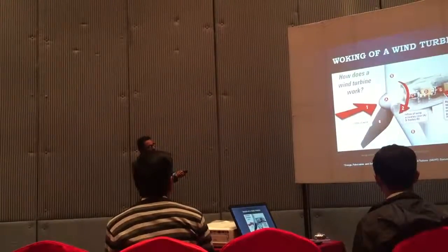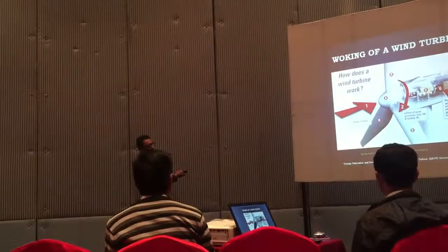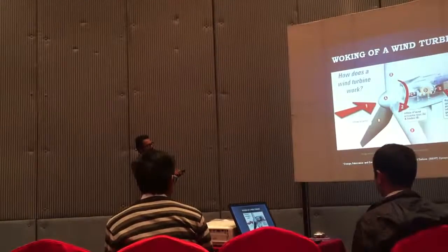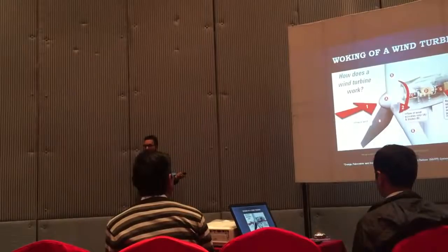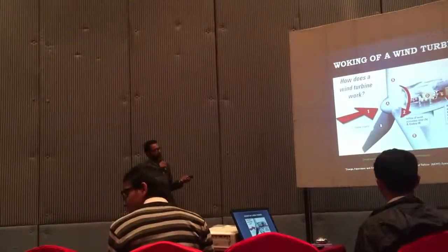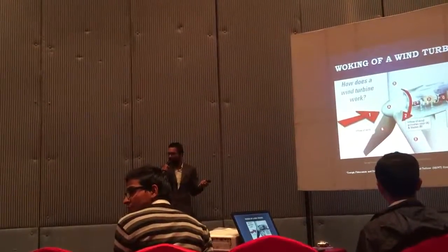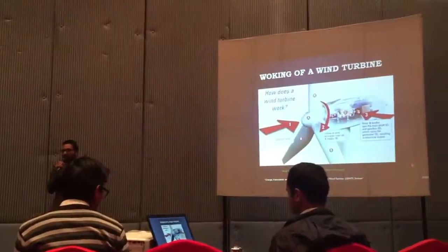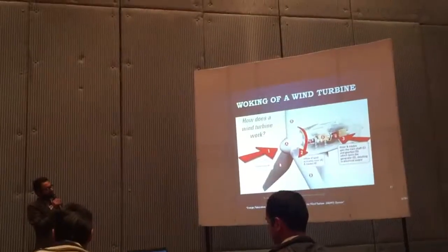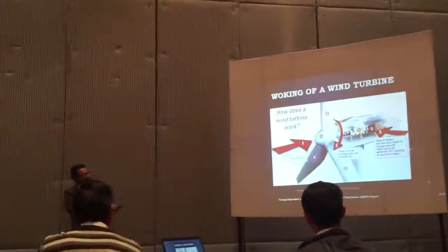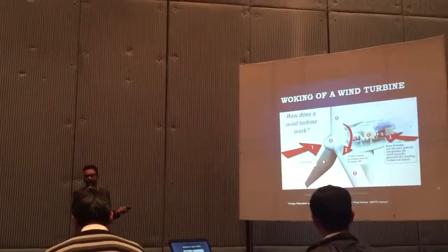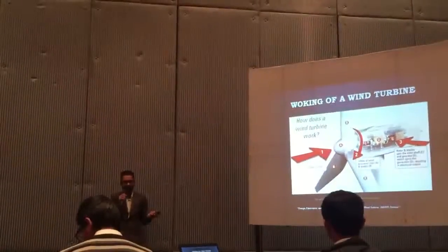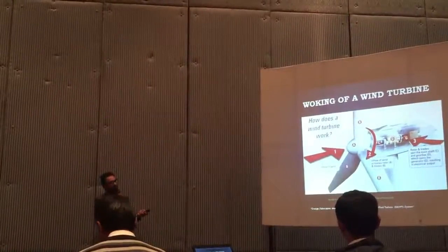The rotor is attached to the main shaft of the body, and the blade is attached to the rotor. The rotor spins, and so do the permanent magnets. The permanent magnets interact with the three-phase coil around the stator, which results in the electrical output. Actually, in our system there is no gear system, so this is just the general overview.